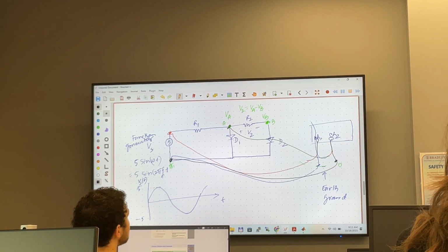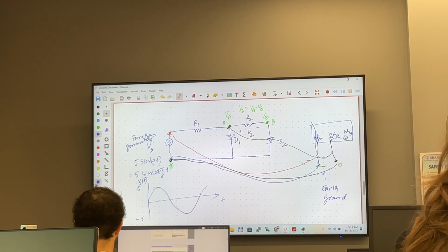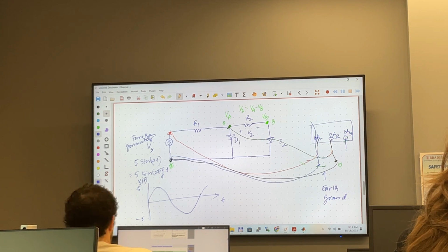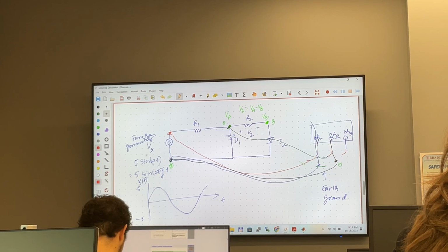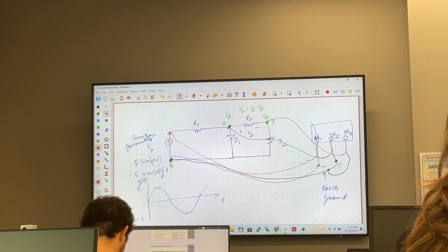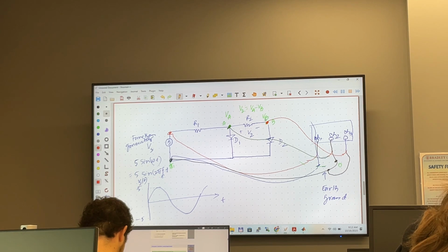And to get the voltage of this point, you have another channel, let's call it channel 3. Okay? So channel 3, the coaxial cable is coming right here. And then you have this positive terminal and this negative terminal. This negative terminal should be grounded, and this positive terminal you connect right here. So now you have this V sub A and you have V sub B.